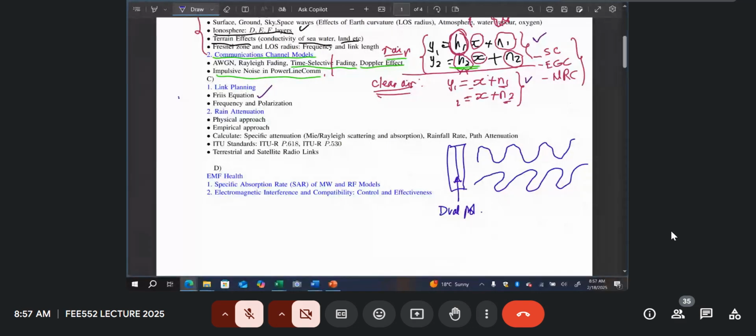This is helpful because within one transmission, you can have two signals going out, S1 and S2. They will not interfere with each other because they have different polarizations, which you can detect at the receiver. So this gives you double capacity. And again, frequency, and of course the wavelength. How does that affect the power that you're receiving?